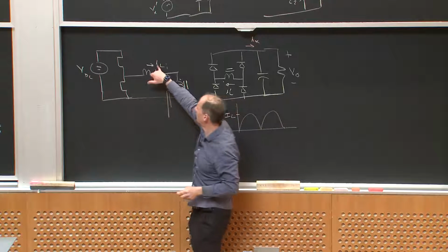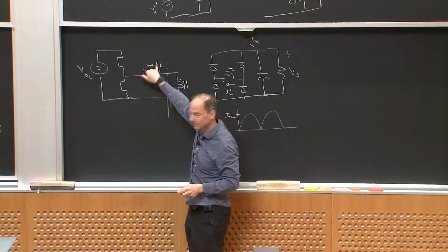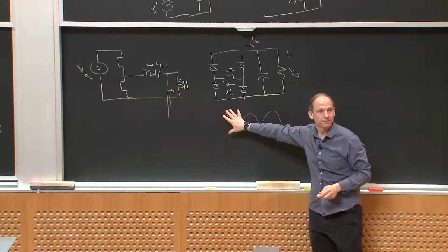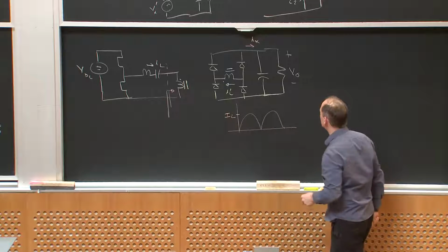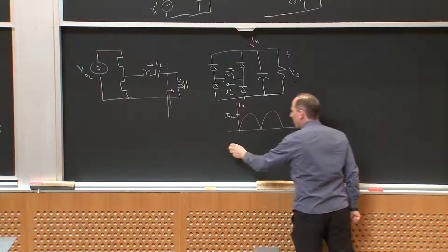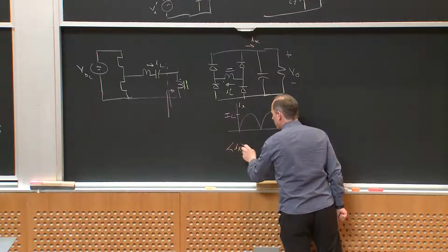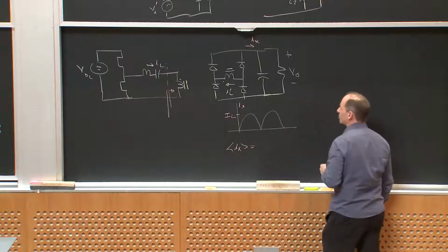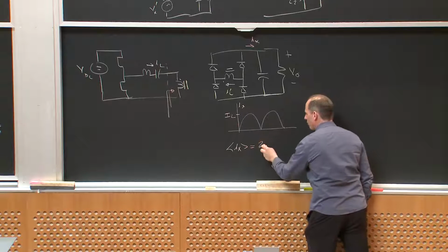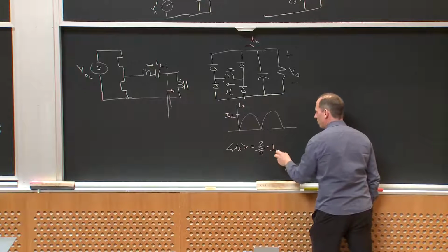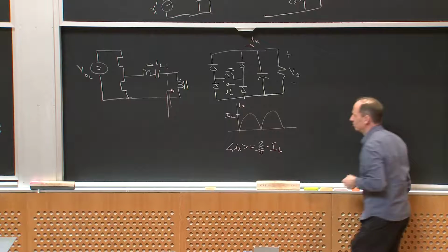So if I sub L has amplitude I sub L, then this just looks like a rectified version, right? The DC current, I'll call this IX, the average value of IX, and I'm running out of time so I don't have a chance to work this out, the average value of IX is simply going to be equal to 2 over pi times IL. I'm sorry, yeah, times IL, right?